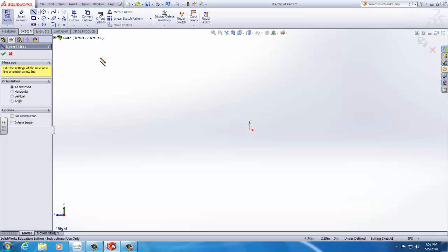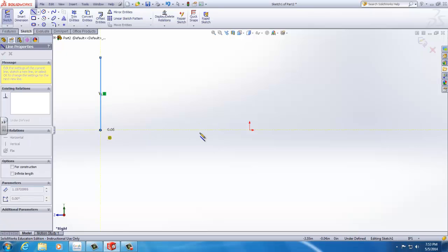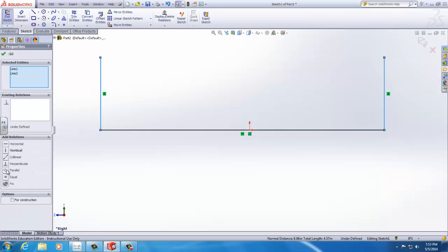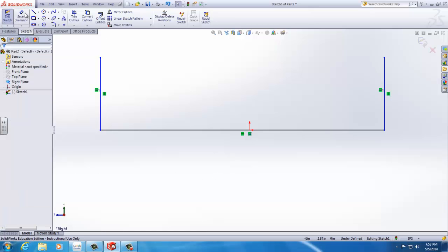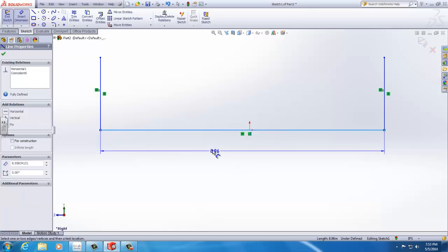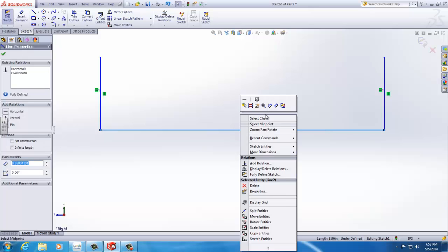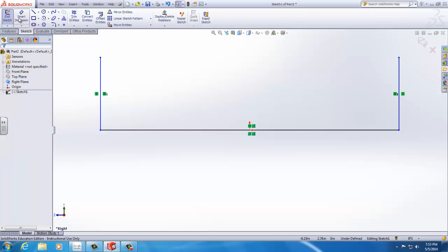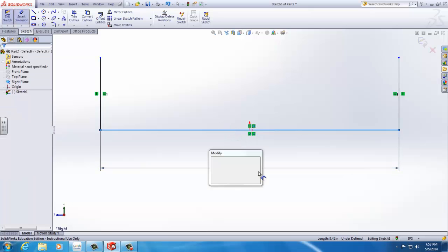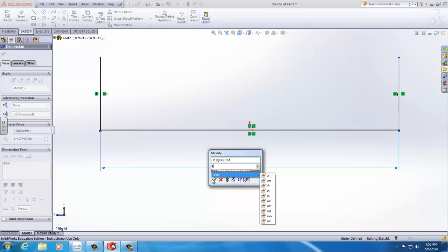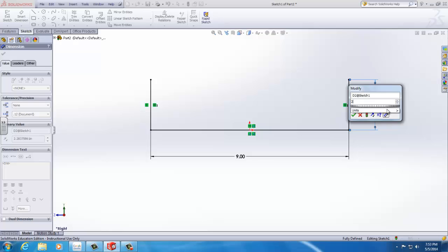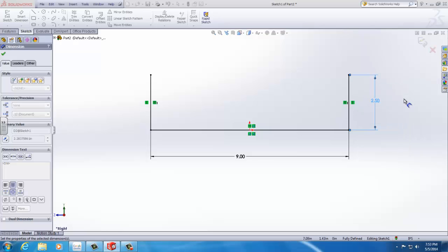So the path will actually be from one side, going down, across the origin, and going back up. We want both sides, and we'll have that option somewhere equal. Now, our next step will be to insert the image. Before I do it, I'm going to make the midpoint and the origin coincident. Sketch tools. Get a distance. Go sketch picture. Maybe a 9-inch by 2.5 inch high.